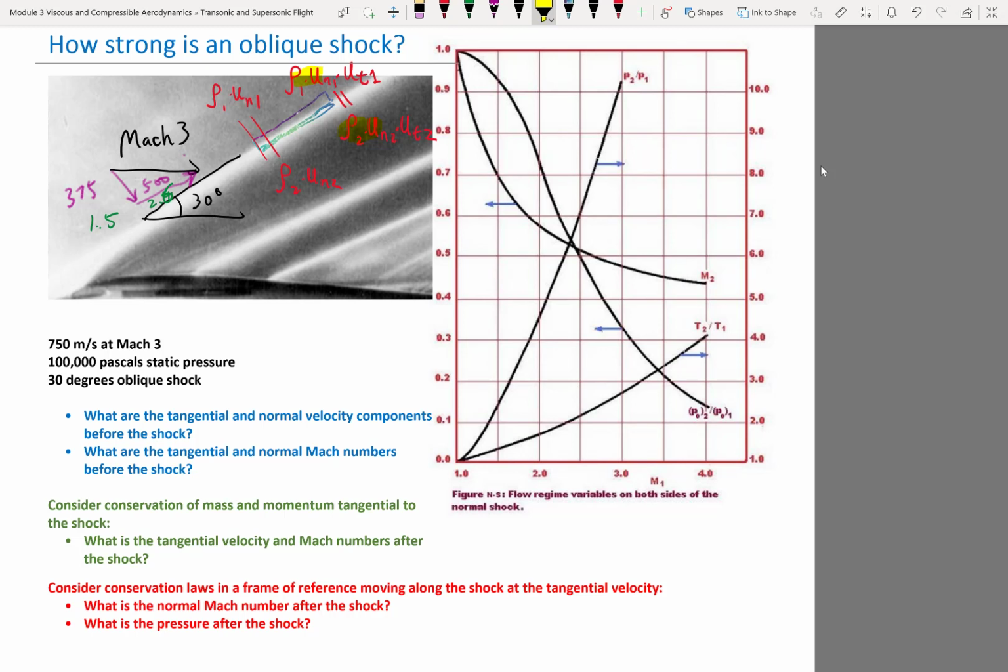And if you have a stagnation pressure ratio of 0.93, you can multiply the stagnation pressure ratio by the ratio of (1 plus (gamma minus 1) divided by 2 times M squared) to the power of gamma over gamma minus 1, right? That's the ratio between the stagnation and the static pressures. You know both M1, 1.5, and M2, which is 0.7, right? So you can do the calculation that way. That'll get you exactly the same line as this, right? So if you happen to have a table that only has the left axis, then you have to do some calculations. All right, any other questions regarding this?